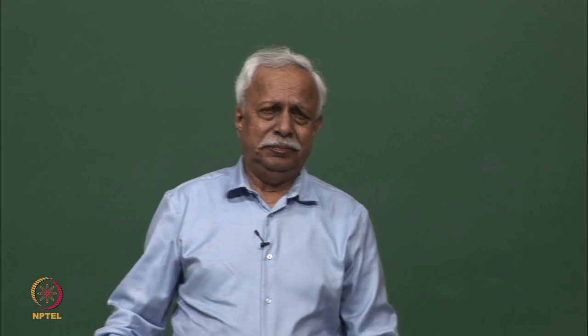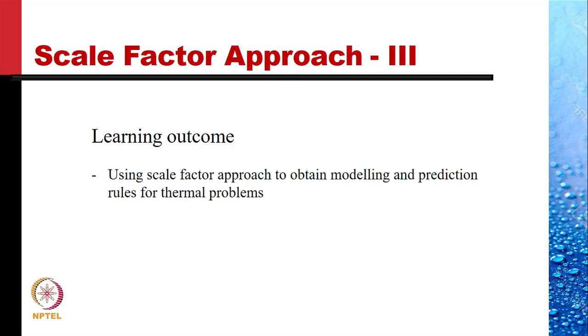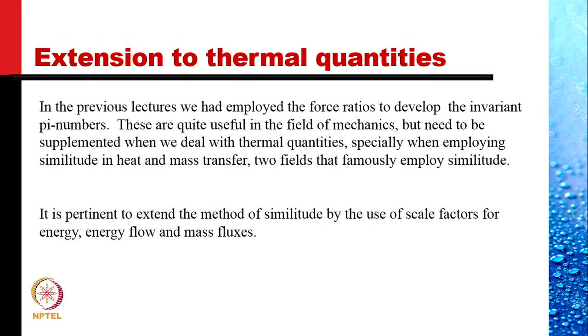Welcome back. Another lecture on scale factor approach, where we would be using scale factor approach to obtain modeling and prediction rules for problems in thermal sciences, heat and mass transfer, for example. In the previous lectures, we had employed the force ratios to develop the invariant pi numbers.